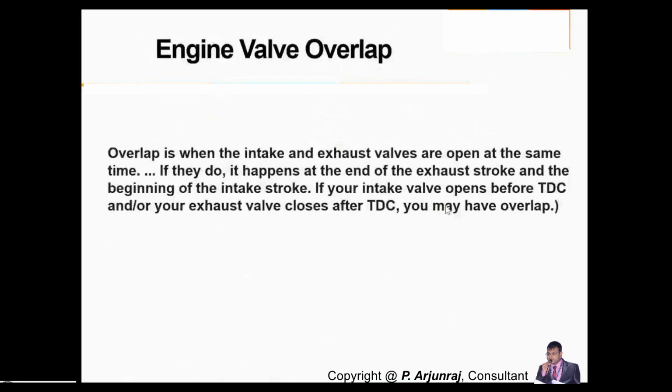So the next important topic is the engine valve overlap. We have seen the engine valve overlap in the valve timing diagram. So what is the overlap? Engine overlap is nothing but, as I told you, the period between the inlet valve opening and the exhaust valve closing basically.